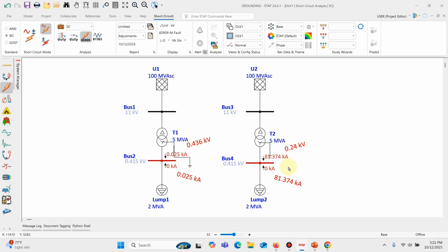So this gives rise to the crucial need to pay attention to your grounding while modeling equipment. This doesn't just apply to transformers. Across all equipment you are modeling. The same system, the same line, the same transformer, the same voltage, but a very large difference in fault current. So if you use the same relay settings for both systems, the relay on resistance grounded feeder might not trip at all because the current will never reach the pickup level.